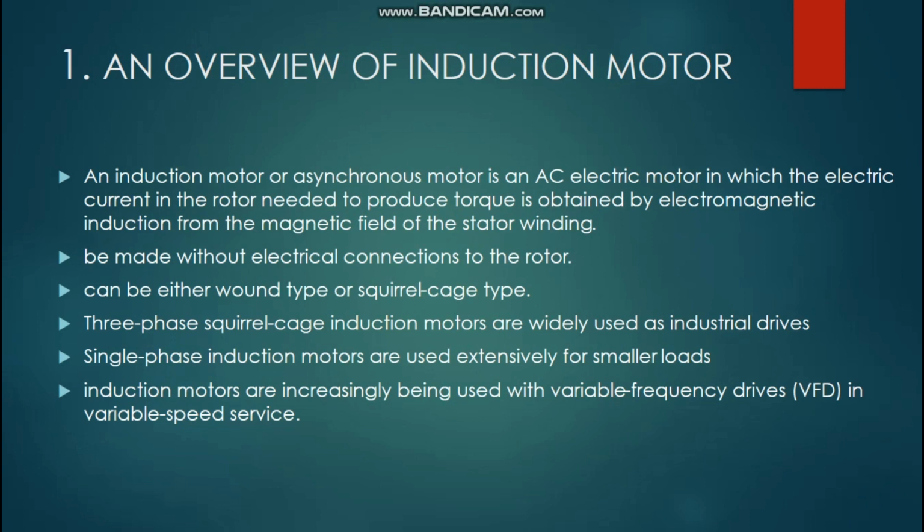The variable frequency drives offer especially important energy savings opportunities for existing and prospective induction motors in variable torque centrifugal fan, pump, and compressor load applications. Squirrel cage induction motors are very widely used in both fixed speed and variable frequency drive applications.